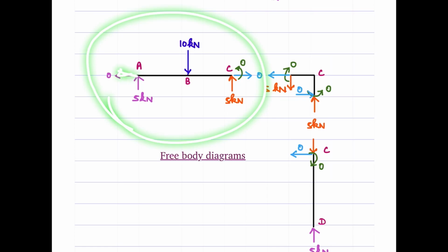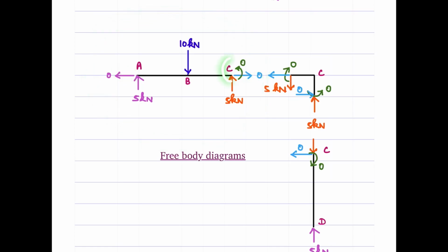So you don't have any axial force here. That means the axial force here should be 0. And if you consider moment equilibrium about this point, you will see that 10 into A is equal to 5 into 2A. This already satisfies the moment equilibrium. Therefore, you don't have any bending moment coming here, right? And then finally, what should be the value of shear force here? It has to be upward 5 kilonewton. Only then this plus this will equilibrate the external load applied here, right?